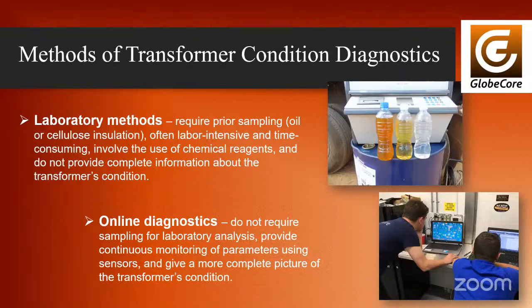In one case, oil tests in the first days of operation showed low moisture, about 10 ppm. A few days later, moisture rose to 60 ppm, which means high insulation moisture. Periodic lab checks did not notice the fast change, and the transformer later failed.